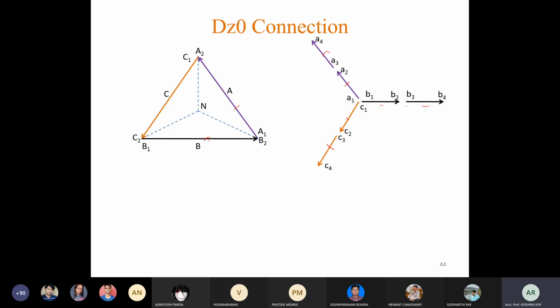So in this type of transformer, all three legs will carry three windings, one for the high voltage side and two for the low voltage side. So this is the orientation of phases before connecting the windings in zigzag connection.